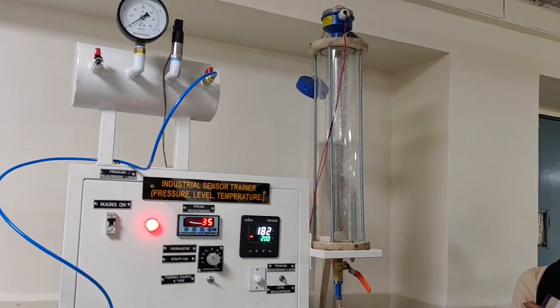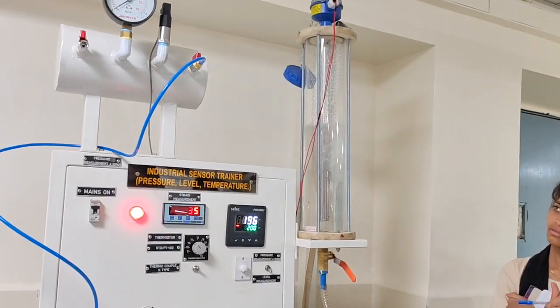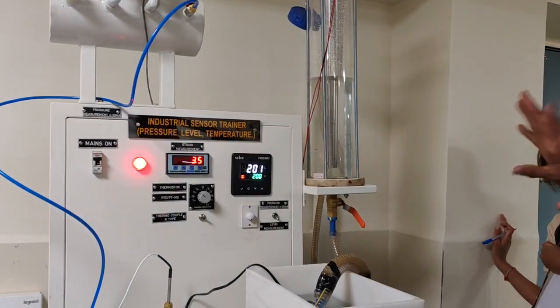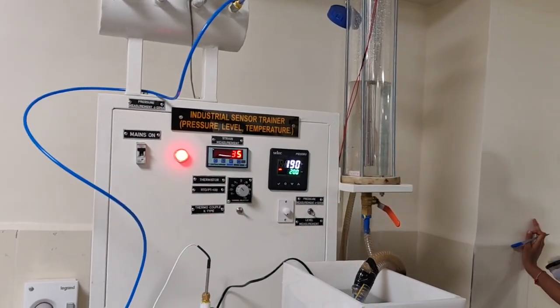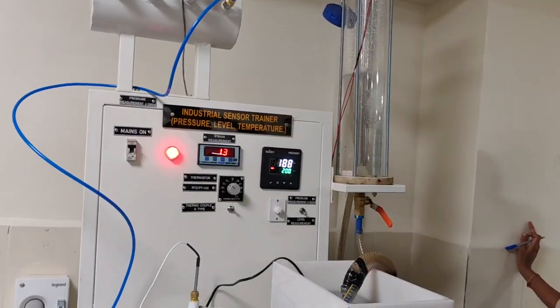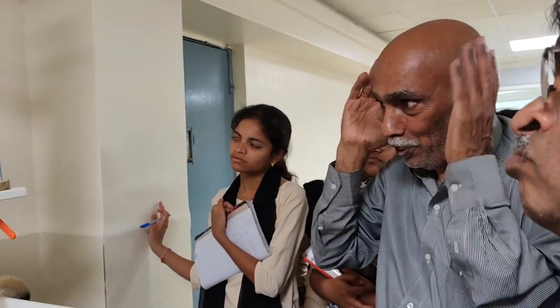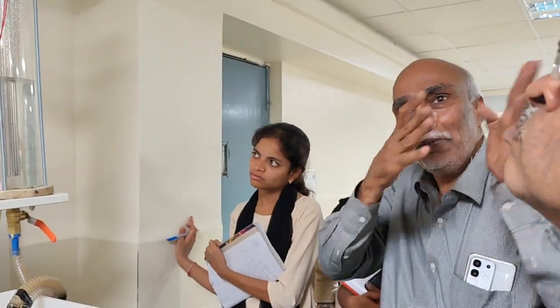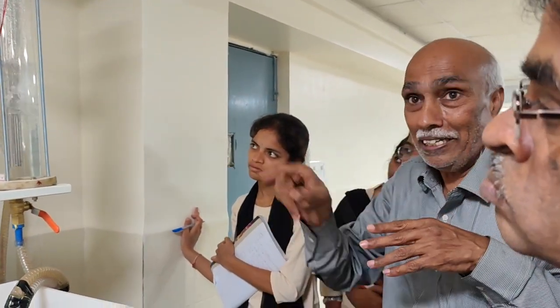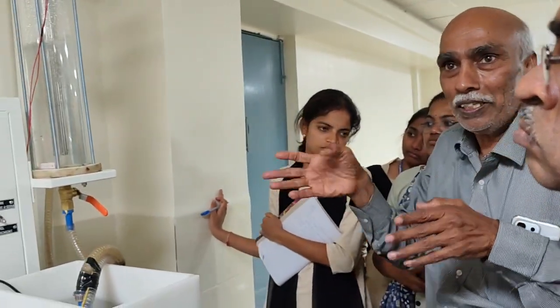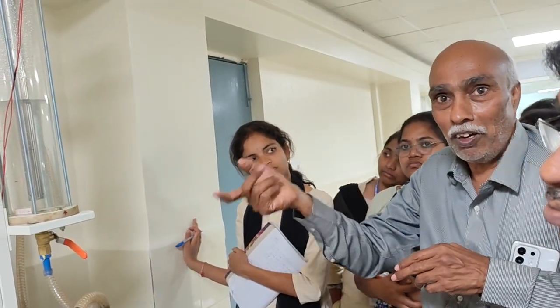It depends, because they need to disturb it and learn it. If you change the derivative time, what will happen to the undershooting? Because you are not running an industry, you need to learn. If you reduce the derivative time, what will happen? If you increase the derivative time, what will happen? All those things they should get training in. Then only they will be able to operate. If some fault comes, they can study what is wrong with the meter and easily sort out the problem. These students have to run automation industry tomorrow. They need to study fault diagnosis also.